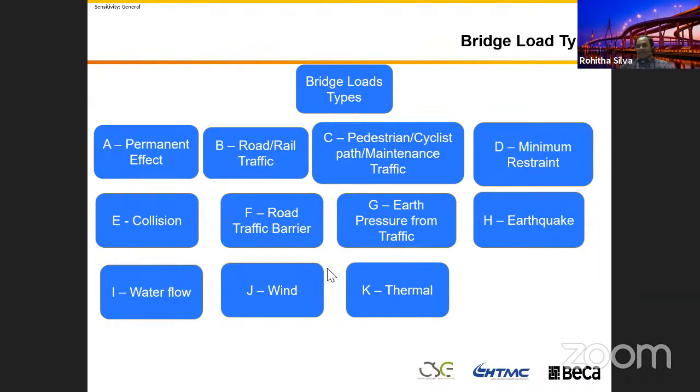And if you combine them together in the bridge design, every section, the bridge will be subjected to a few thousand load cases. But don't panic when you are designing a bridge. With experience, if you draw a sketch and use your structural analysis knowledge, you can identify only very few load cases that govern the bridge.